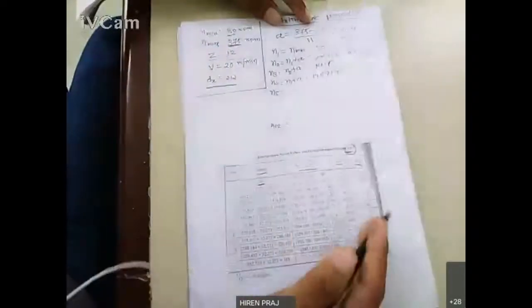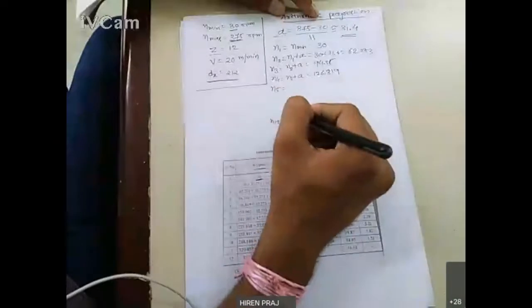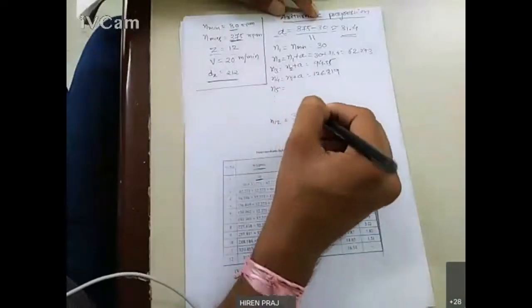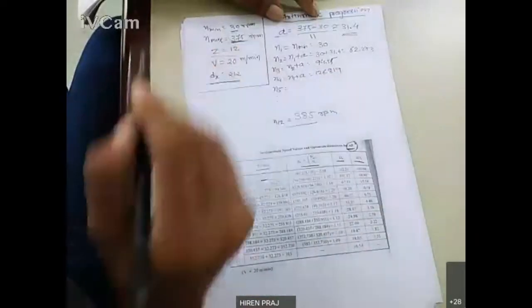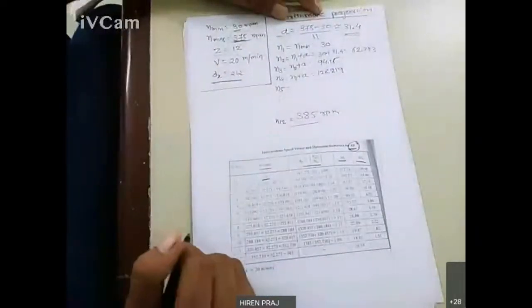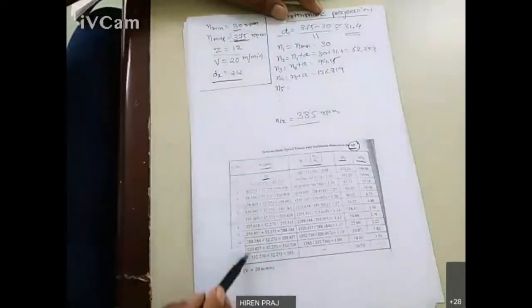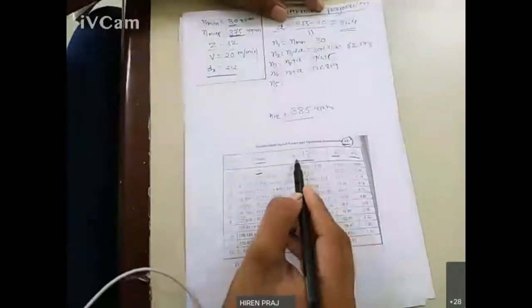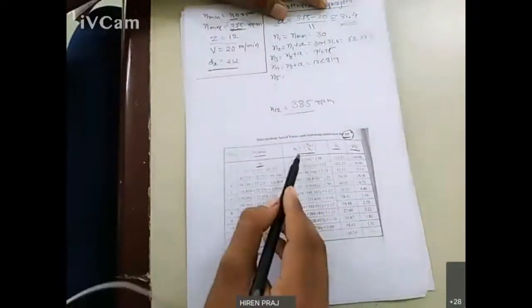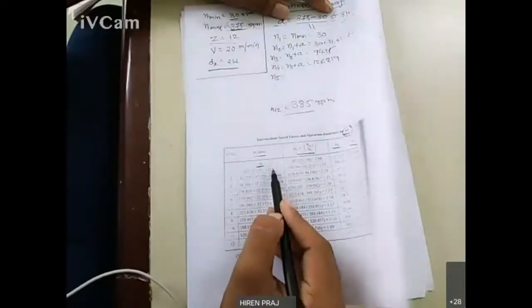But in your case, if you are following this arithmetic progression constant, then your final speed you get is 385 RPM instead of 375, right? So these are the different speeds available based on the arithmetic progression series. They are listed in this column. Now next is the phi progression, or the speed ratio between two RPMs.